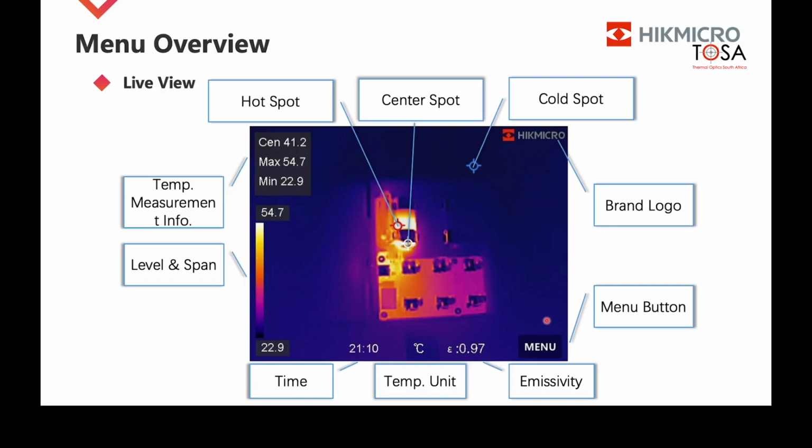Plastics typically has a high emissivity, which means that it radiates a lot of the thermal properties in the form of infrared light towards the camera, and we're going to see that. In the middle you see the temperature unit. We are of course measuring in degrees C here.